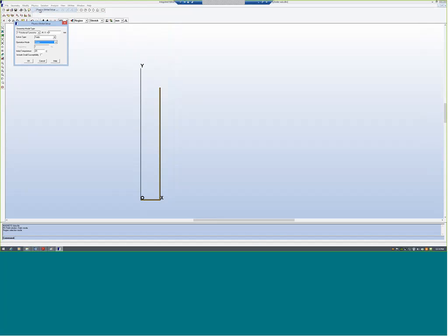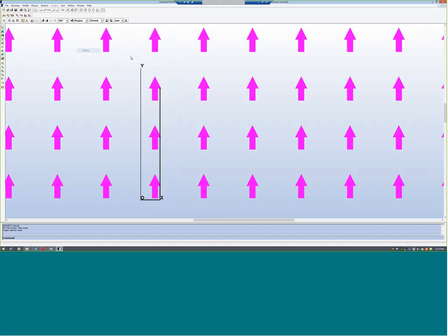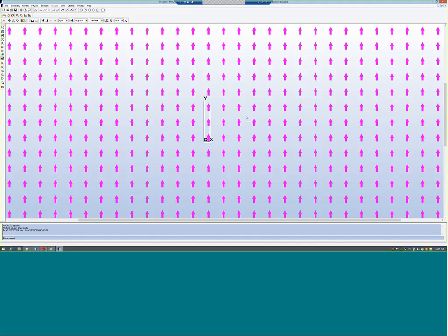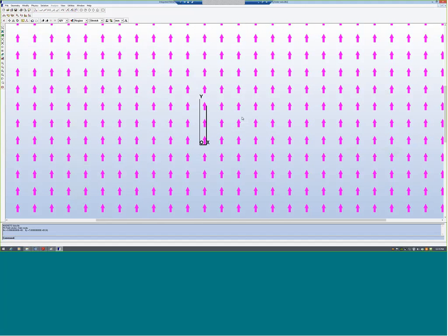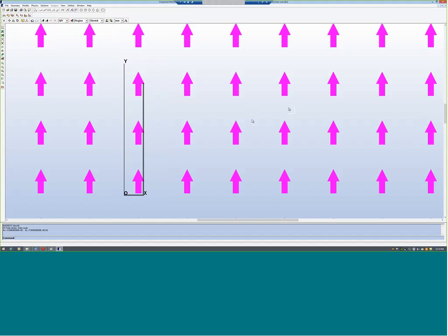Okay, physics global setup. You see here Y rotational symmetric, and other facilities are 2-dimensional, so you can use it, or X rotational or Y rotational. I prefer Y rotational. In physics, I used impressed fields in this case. If you see here, everywhere there is an impressed field of, I think I took 5 Gauss. It can be anything. I've got a 5 Gauss field there.